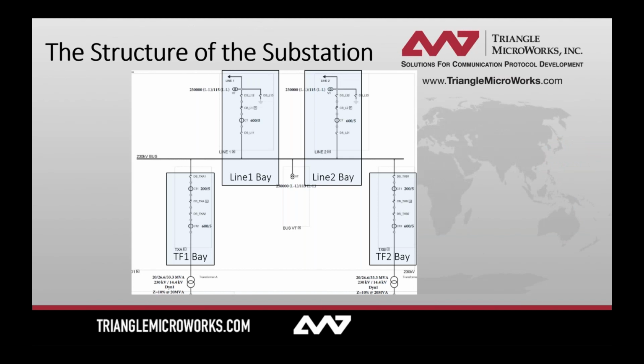In the last webinar, we designed a high voltage side of a substation. It has 2 transformer bays, 2 line bays, and a bus bar with differential protection.